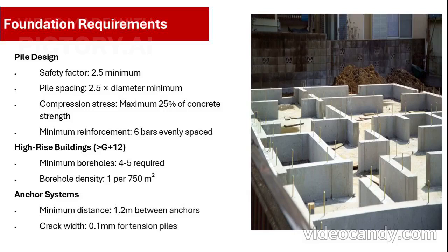For pile design and compliance with the Dubai Building Code, a minimum safety factor of 2.5 is required. Pile spacing should be at least 2.5 times the pile diameter, and the maximum allowable compression stress on piles is limited to 25% of the concrete's compressive strength. Each pile must have at least 6 reinforcement bars evenly spaced for structural integrity.